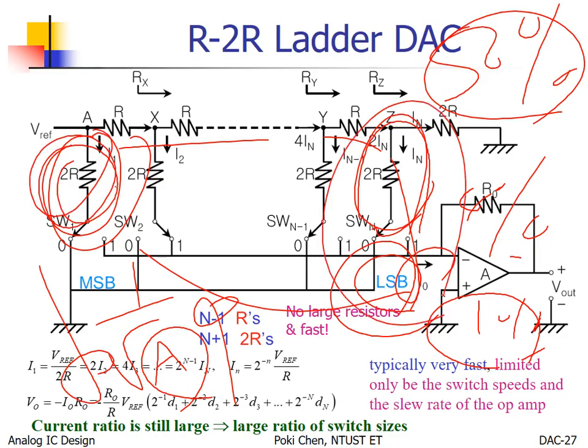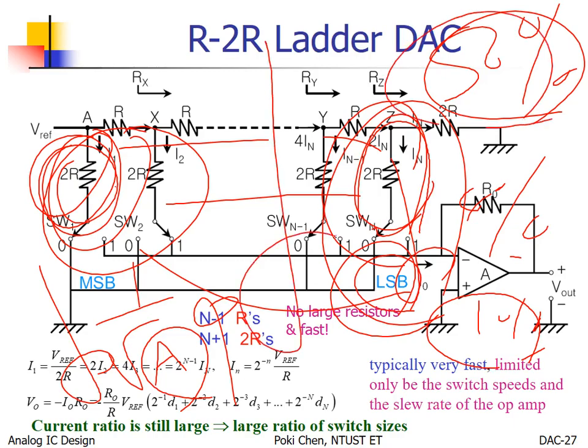So, for LSB, we had better reduce the chip area, and the area we saved from LSB, we can allocate to MSB. In brief, we have larger area for MSB, smaller area for LSB, and overall, the error will be reduced.